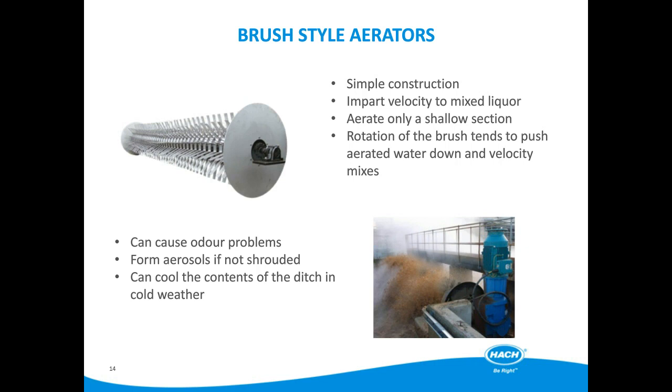Brush rotors are installed along with a submerged baffle to deflect the flow of aerated water towards the base of the ditch, causing turbulent flow, providing both mixing and the required velocity to maintain solid suspension. The location and angle of this baffle is critical for the efficiency of the aerator, and being submerged, this is a vital piece of infrastructure which is often forgotten. It's also noted that the UK and Germany are the largest users of brush rotors in Europe. However, brush rotors are considered to be an old technology by many manufacturers.